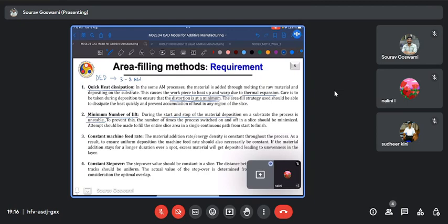As such, there may be bulging at certain points, so you have more and more material being deposited, or there might also be depression. And either of these is actually a defect because it is moving away from our design geometry.